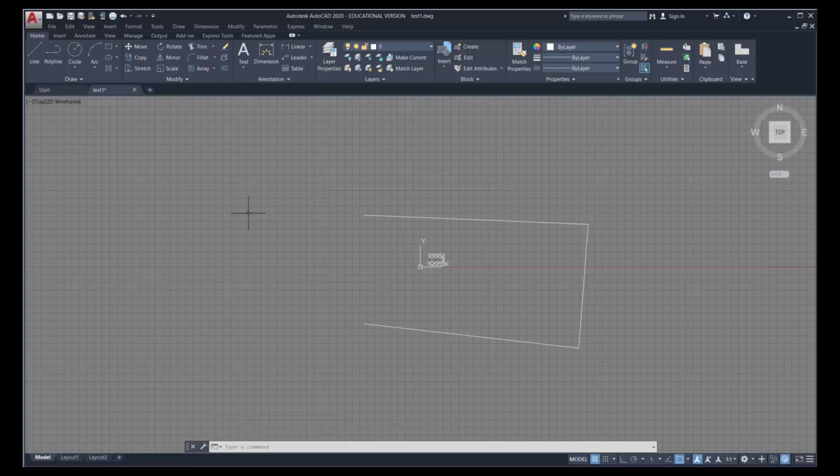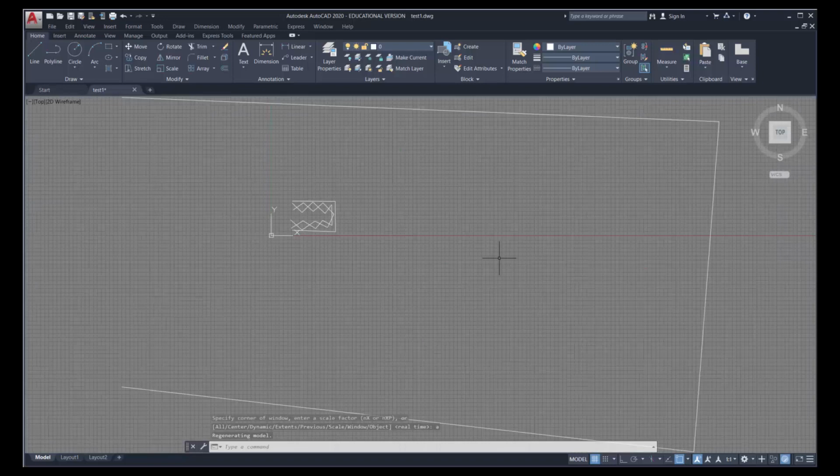Now, for those of you who did not click on the line command, you were just clicking in space. So here I have the drawing. It's slightly larger. If I type in Z enter, A enter, now it zooms to the outer perimeters of the lines that I've just drawn. If I erase those lines, I can use the erase tool, but I'm going to show you another way of erasing the lines. And some of you may have accidentally experienced this.